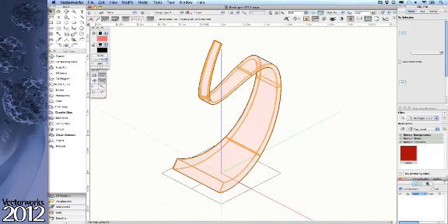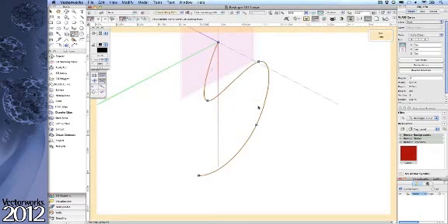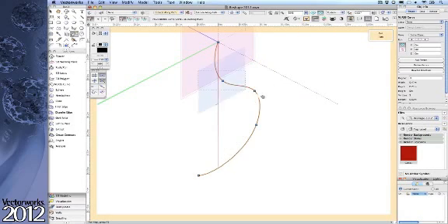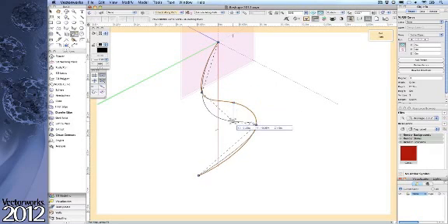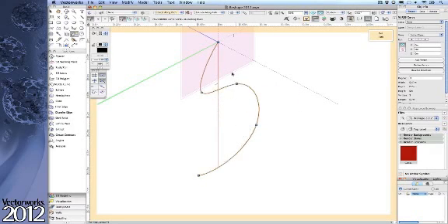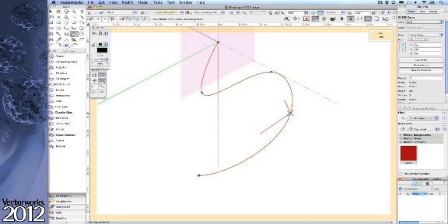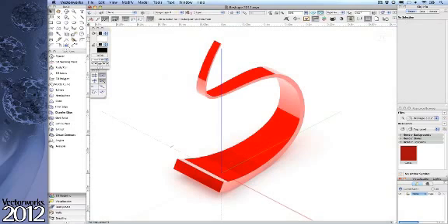We've also improved the editing interface when it comes to working with NURBS-based objects. Once you're in the editing mode, you can choose to edit just one node, or multiple nodes, just by including them in a marquee selection. Once again, this seemingly small improvement can really move your productivity along, giving you the opportunity to explore more options, resulting in better designs.